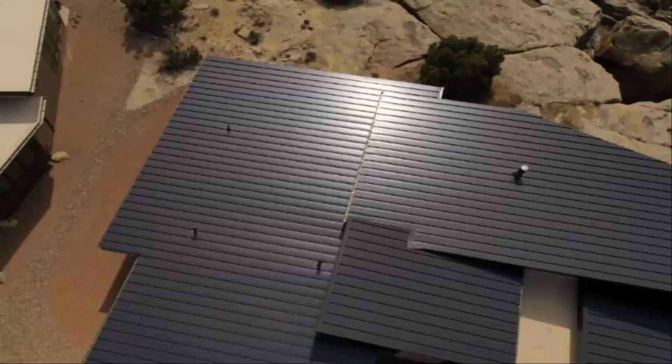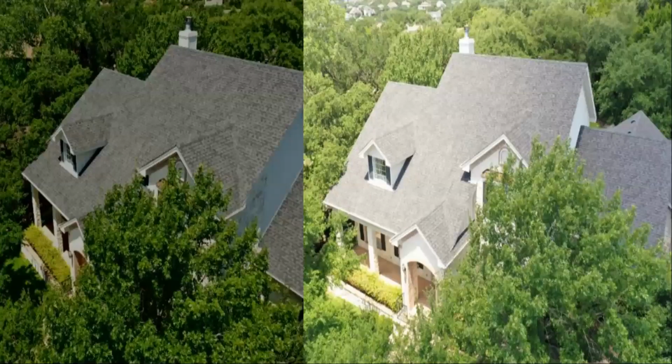Beware of light reflecting off of a metal roof and affecting the camera's lens. And then significant or intermittent cloud coverage or flying at dusk can lead to some images being dark. And that lighting difference, whether it's darker or lighter, will create color inconsistency and can lead to texture map discoloration and possibly even a modeling error.